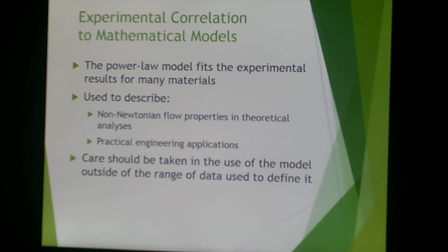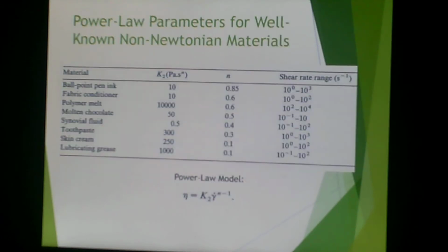The power law model fits the experimental results for many materials. It's often used to describe non-Newtonian flow properties in theoretical analyses and in practical engineering applications. I use it extensively when doing capillary rheometry. But you do have to be careful in using this model outside of the range of data used to define it. And they all have limitations in that regard.